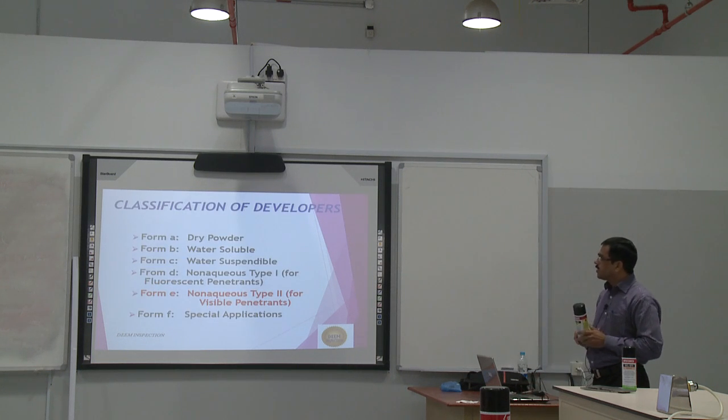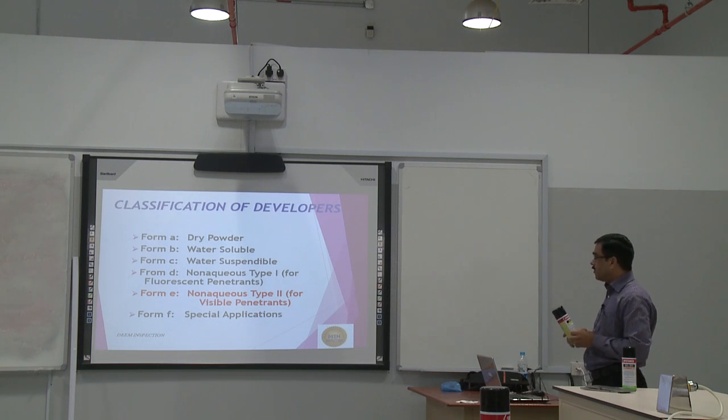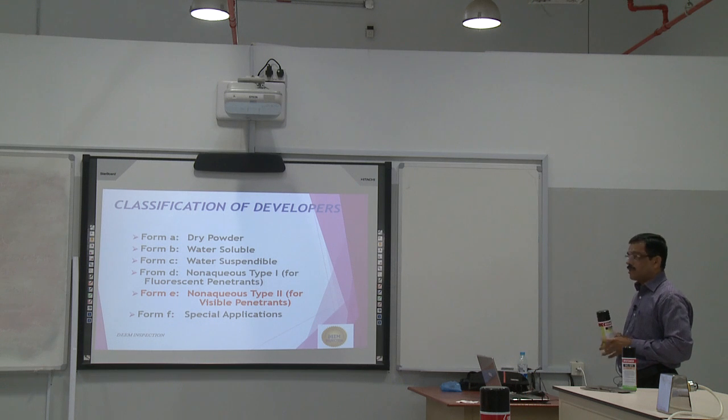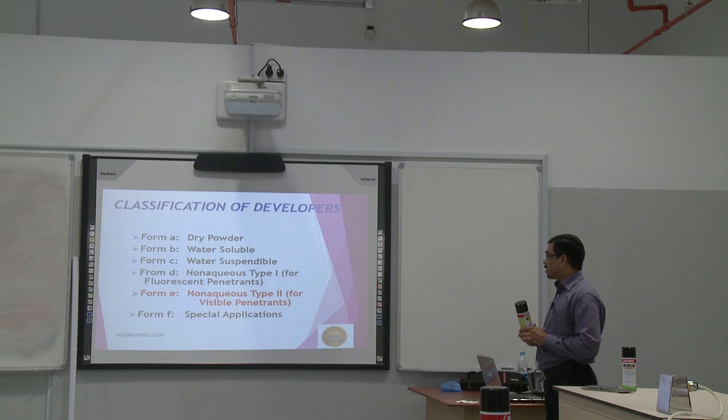Just a classification of the different developers: dry powder, water soluble, water suspendable, non-aqueous type for fluorescent, non-aqueous type for visible, and special applications. In this case, ours is form E. We are using non-aqueous. Non-aqueous means solvent based. So non-aqueous type 2.